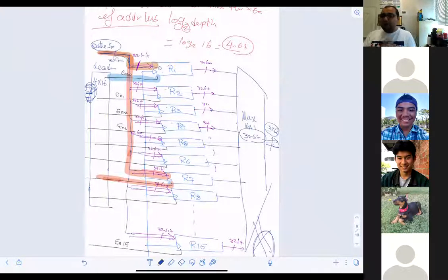It's a set of flip-flops sharing the same clock, so that means they are synchronized. We said the right candidate to be used for building a register is the D flip-flop. Then we came to the point of how we can communicate with the input and output, and we defined the configurations as serial input serial output, serial input parallel output, which is SIPO, parallel input serial output, which is PISO, and parallel input parallel output, which is PIPO.